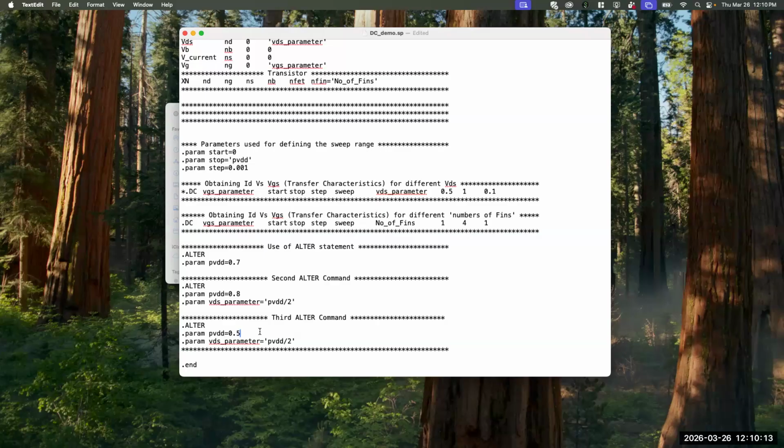So all I had to do is basically take that file and just keep running simulations until that transistor hits saturation. It was super simple. Otherwise, I couldn't even think of a good way to check for saturation in that transistor. So there is a reason why they have features. They know some people care about it.